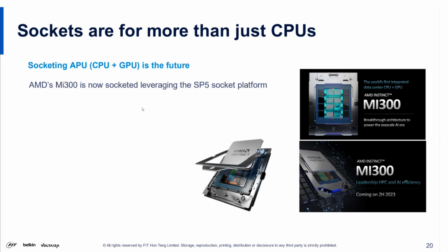In that instance, they made some slight changes to the loading hardware in order to utilize a similar design for their APU, the MI300. And that's the trend that we're seeing, getting away from direct attach GPUs, if you will, or APUs as well, and socketing them to allow customers to do upgrades or system replacement without having to desolder.